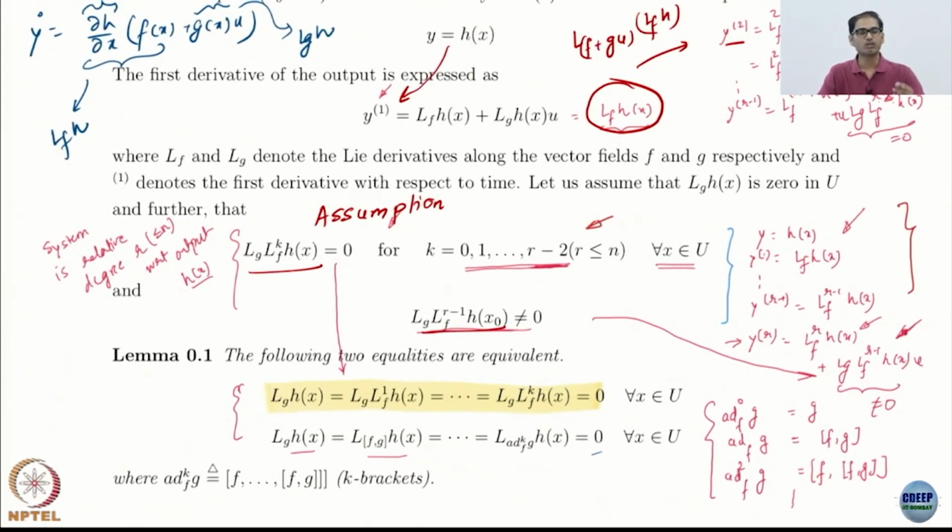We essentially try to compute the relative degree by seeing how many derivatives of the output you need to get to the input. And we then say that this is the part of the dynamics that you can actually linearize via feedback. So this r, the dynamics of size r, is what you can linearize. So it's like a partial feedback linearization, and the rest of it is some additional dynamics.